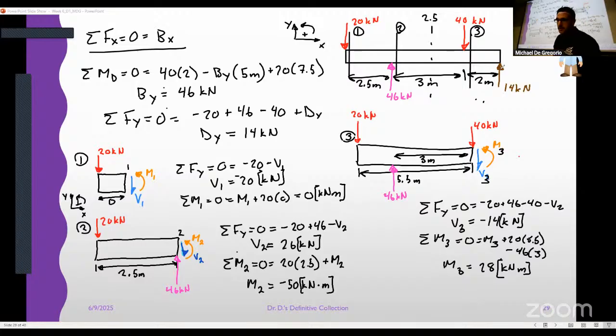What about the shear? There's only one force. If I look at the other side, it's 14 kilonewtons. So it's the same. When you do the math, it'll flip over and be negative. So it checks out. So you could have done it on the other side. Again, personal preference, doesn't matter. For teaching purposes, I think it's nice to show the progression as we move along the beam.